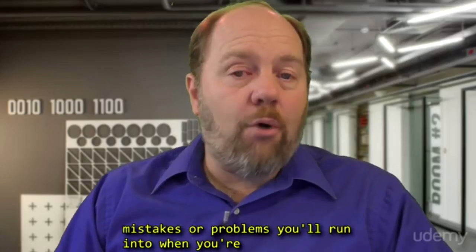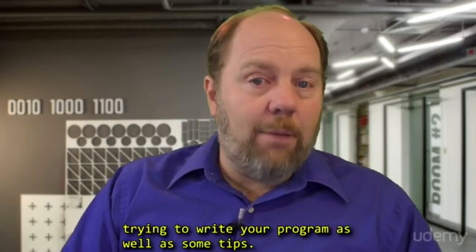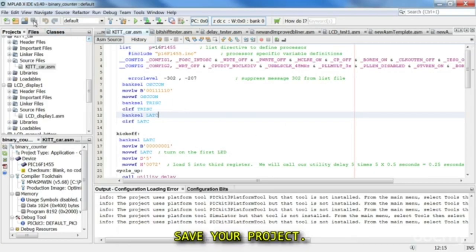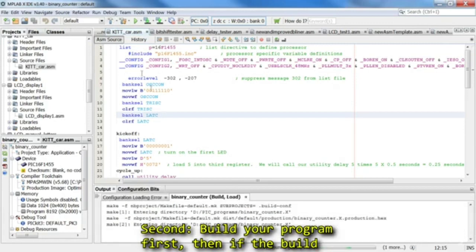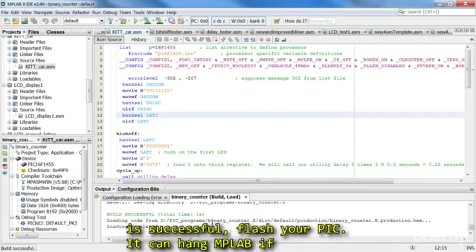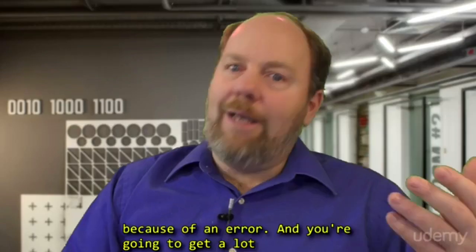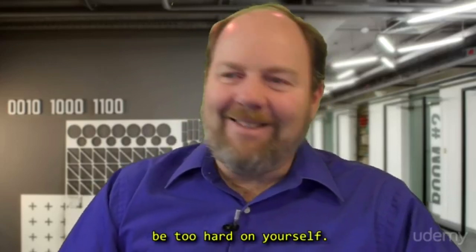I'll give you some common mistakes or problems you'll run into when you're trying to write your program, as well as some tips. Before you try to flash your PIC, save your project. Second, build your program first, then, if the build is successful, flash your PIC. It can hang MPLAB if you try to flash your PIC and the compiling fails because of an error. And you're going to get a lot of errors. That's just part of programming. Don't be too hard on yourself.